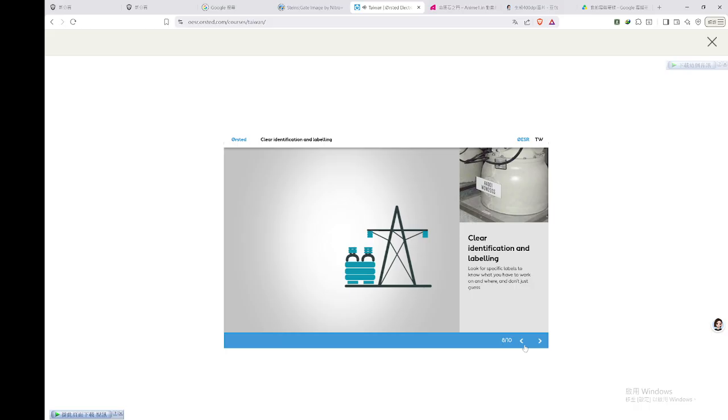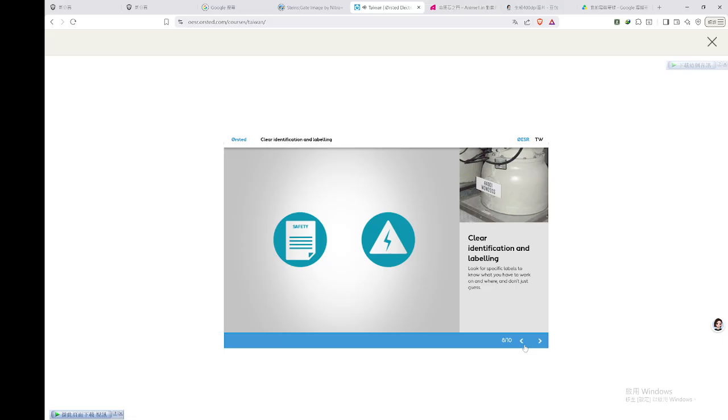For example, substations of the open compound type contain many pieces of technical equipment that are identical in make and version. When servicing or repairs are done under a safety document, it's often the case that most of the technical equipment remains live, and only a small part of the substation specific to the safety document is de-energized and earthed. So confusion about which piece of equipment should be worked on could be disastrous and lead to death or injury.